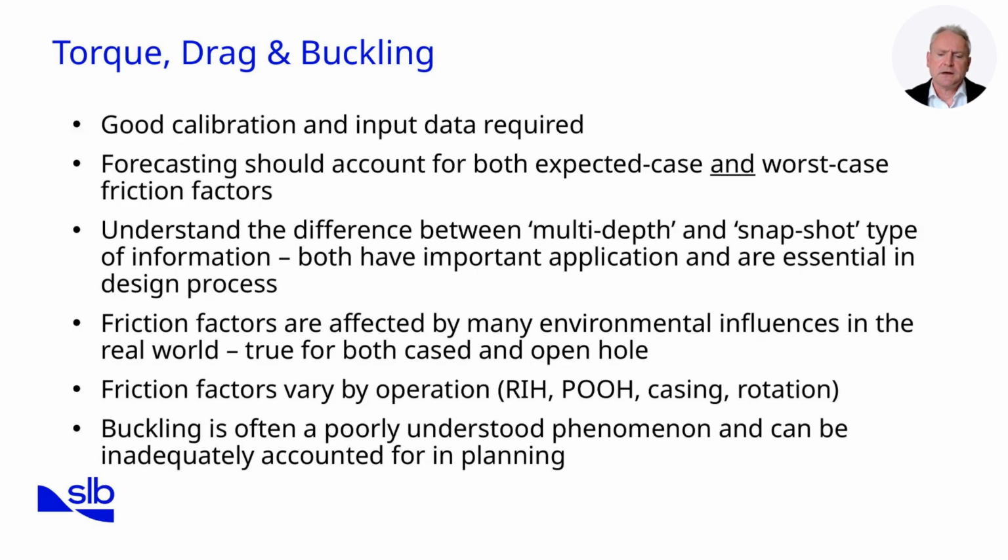Buckling is often poorly understood and underestimated. Without proper modelling, drill pipe or casing may reach critical loads, resulting in sinusoidal or helical buckling that impairs tool movement and increases wear. Effective management of torque, drag and buckling requires robust design, real-time monitoring, and proactive operational practices. Next, we'll look at wellbore instability, another risk that becomes more pronounced in high-angle ERD wells.